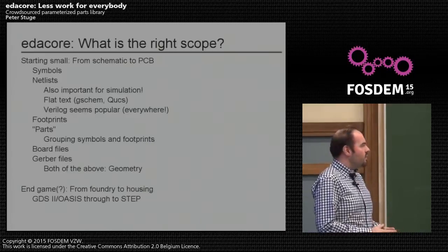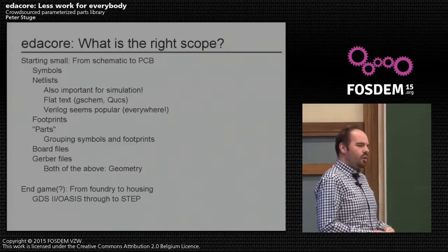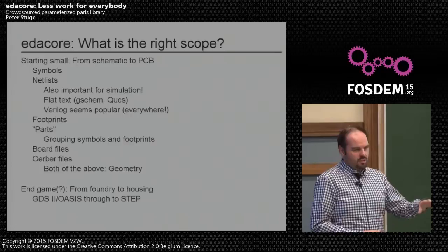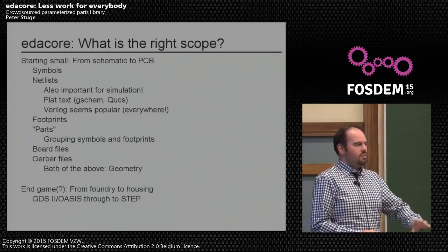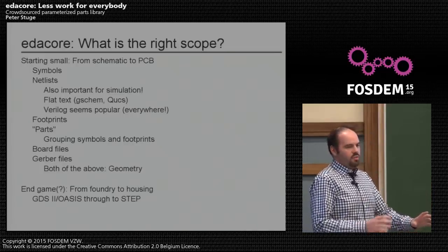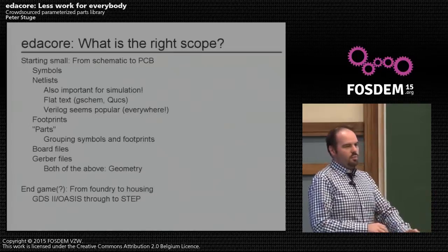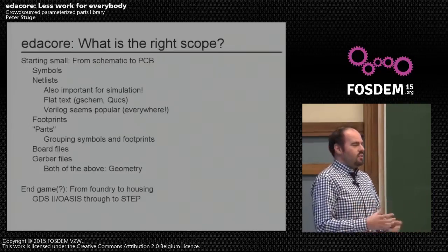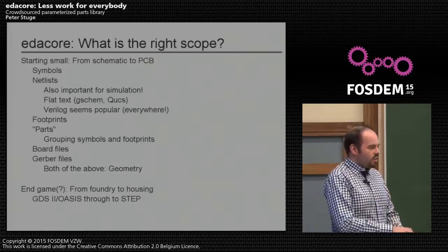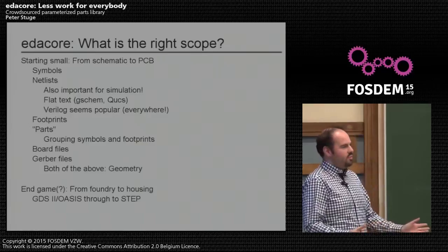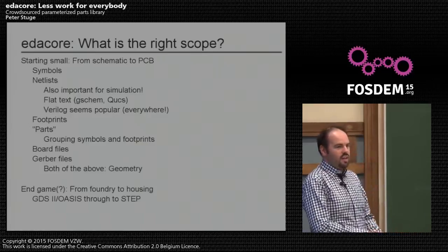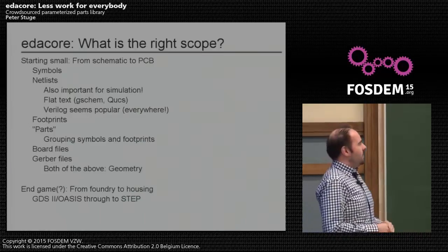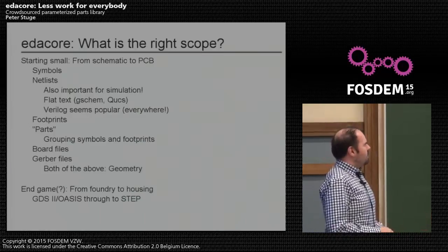So different kinds of packages for a particular part, perhaps, are needed. If you have in the schematic, you want to say, I'm using this circuit, this IC, but at that point, you don't care what package it is in the board layout. You do. Still, this needs to be the same. It is the same circuit. So for simulation, you don't want to have two different ones. You want to still have just one. And the vendor will also probably only have one model for this. So yes, need to keep this in mind.